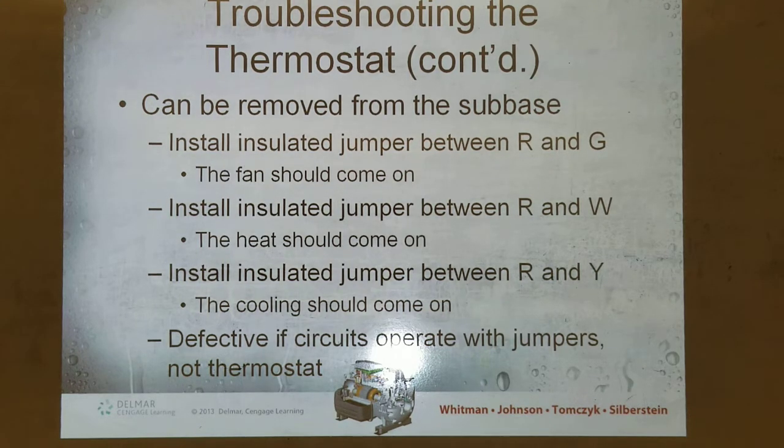Wait, question. If I put them on, should the system turn on right away? It's just a dumb question. I'm just saying, what if there's a lag? No, there's not going to be a lag. It shouldn't be. Either it's going to work or it isn't. So then you're eliminating any potential problem right there by removing the thermostat from the subbase.